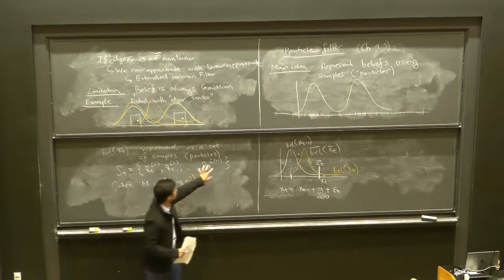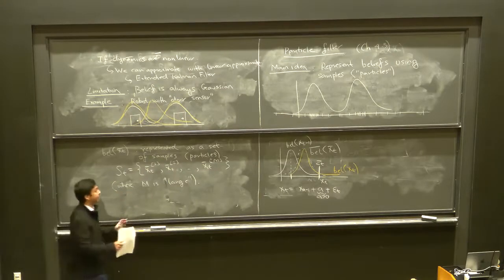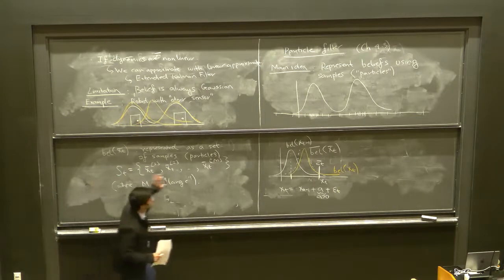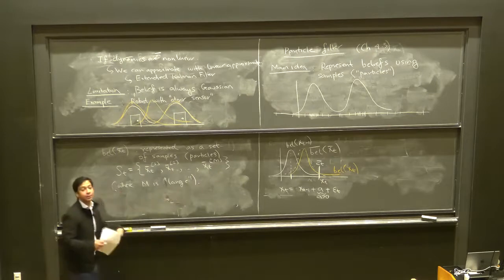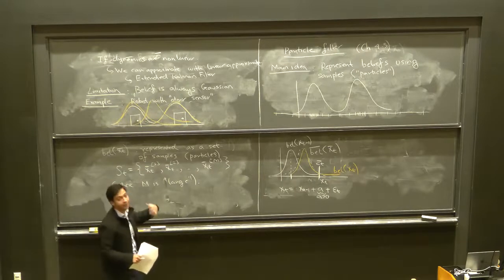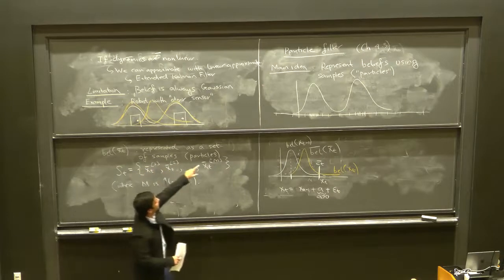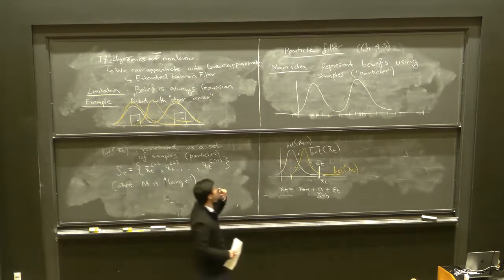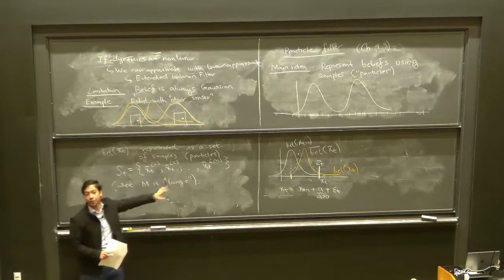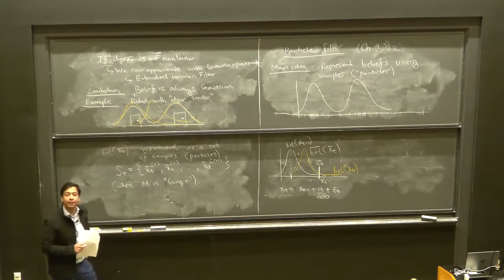But all right, so I guess the main point is that we're going to change our representation of the belief. So instead of saying that our belief is going to be Gaussian, like with the Kalman filter, we're going to say that our belief is represented by some set of particles, and we're just going to keep updating that set of particles at every time step. We're going to do a dynamics update, a sensor measurement update, but at every time step, we're not going to explicitly represent some complicated distribution. We're just going to approximate some potentially complicated distribution with a finite number of particles.